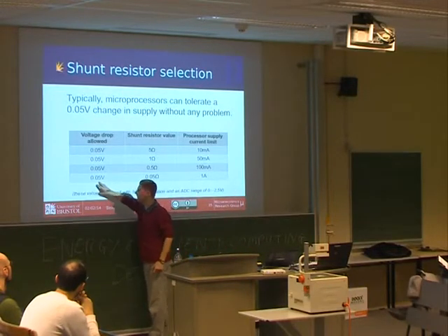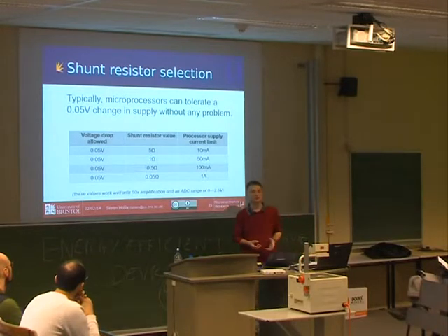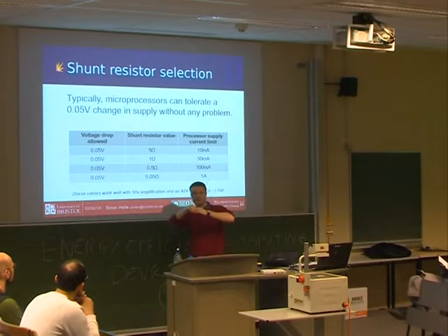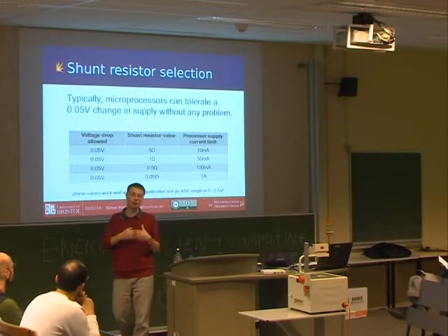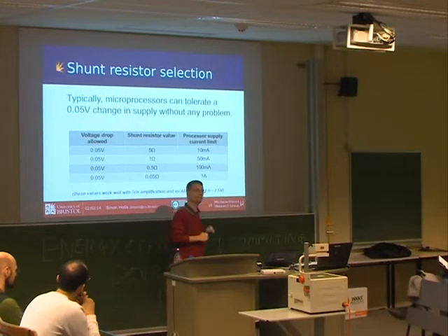So what you're now doing is feeding this kind of voltage into the ADC in a microprocessor, which has a range of 0 to 2.5 volts. So you're using some tiny, tiny part of that range. What you want to do is maximize the part of the range that you use, because that gives you more resolution, more points inside the range that you can discriminate.